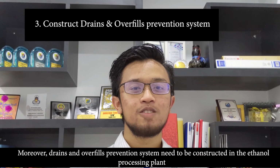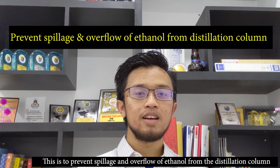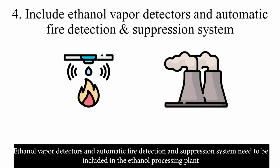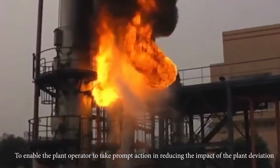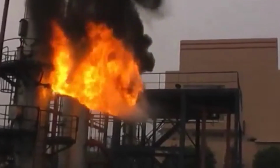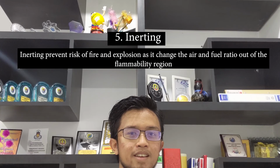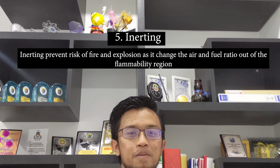Moreover, drains and an overfill prevention system need to be constructed in the ethanol processing plant. This is to prevent spillage and overflow of ethanol in the distillation column. Ethanol vapor detectors and an automatic fire detection and suppression system need to be included in the ethanol processing plant to enable the plant operator to take prompt action in reducing the impact of the plant deviation. Inerting prevents risk of fire and explosion and moves the air and fuel ratio out of the flammability region.